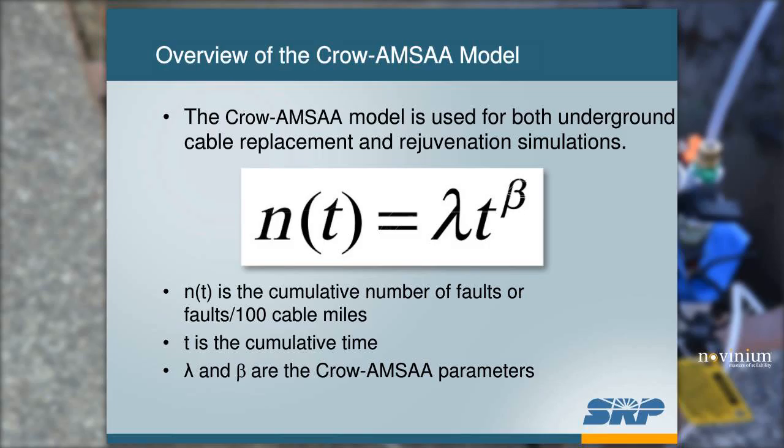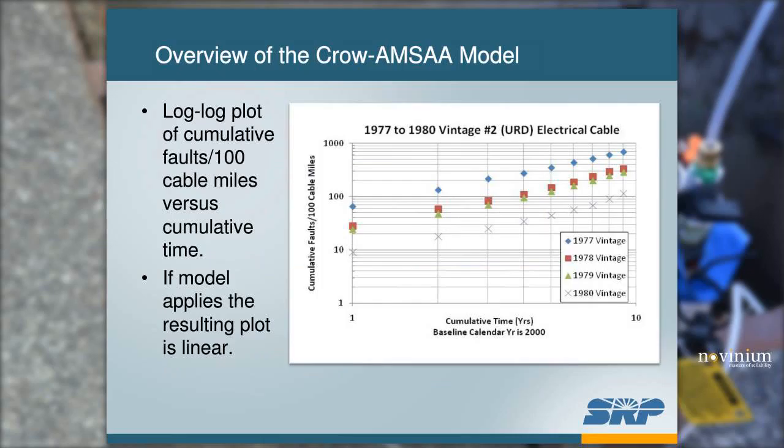The other problem that you have with the model is defining the replacement unit. I've seen several people out there want to take a continuum of cable and just arbitrarily define it as a set length of like 1 foot, 2 foot, etc., whatever the length of the splice is perhaps. Again, you cannot do that with those type of models because you're changing the distribution. So with repairable systems, a reliability growth type model, such as a Crow-AMSAA, is a preferred model.